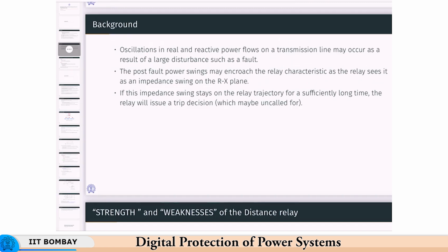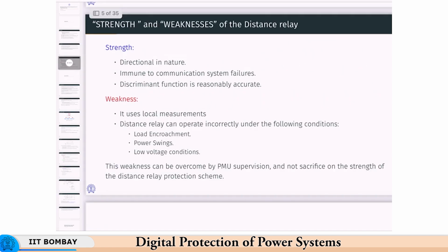So, if it is a power swing, can we use the information from last time, where we classified the relays as vulnerable, or the same information processed in a different fashion, to block the relay from operating if it is some event other than a fault?